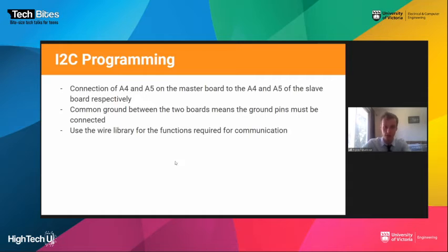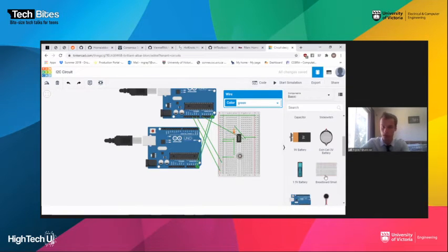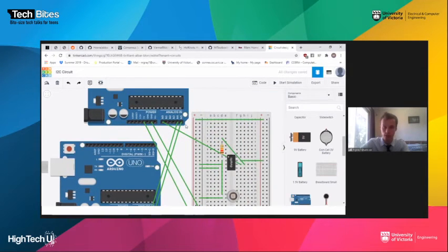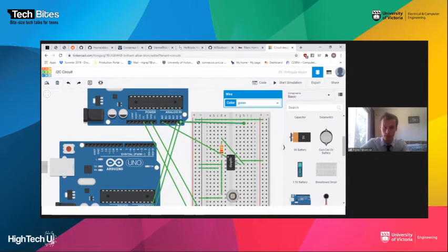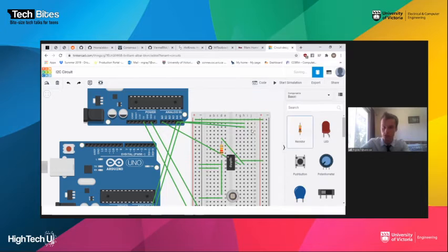So let's connect those. So for the pull-up resistors, what we can basically do is connect each of these pins to here. So you can get this. And just connect 2 resistors to ground.